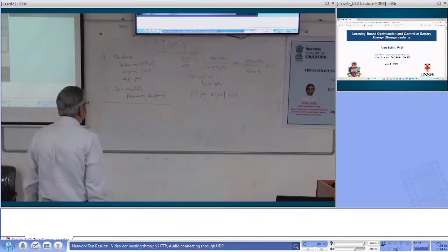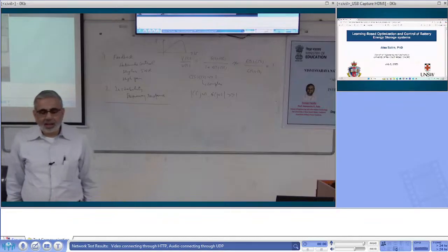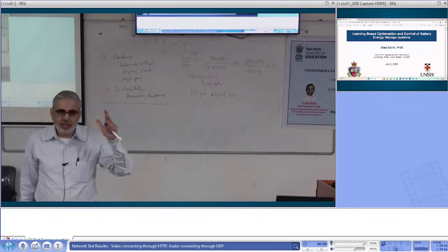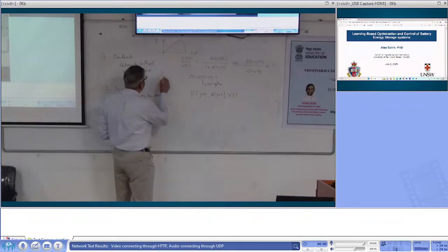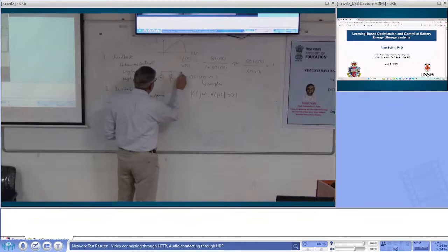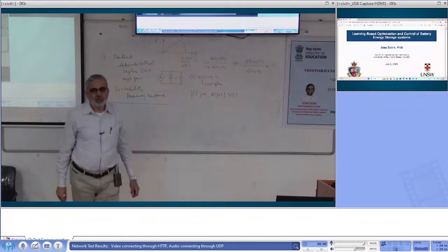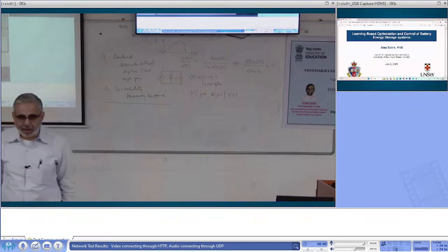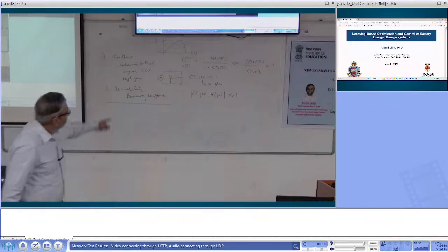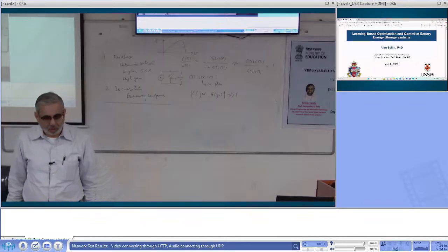So if I can say it in my words, we connect the diode in forward bias, right? And the current due to solar radiation is constant. Because that current is constant, the more you increase the voltage across the diode, the more power you can extract. The current is going that way, so it is charging the battery. But as soon as the diode comes into action, as you said, diode forward bias current kicks in, the net current going through the battery becomes smaller and smaller, and you lose all power. Okay, so we saw that.